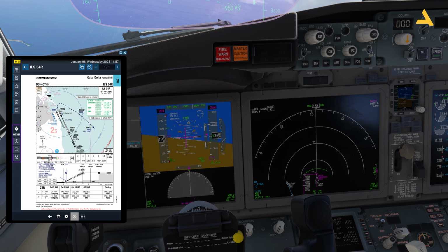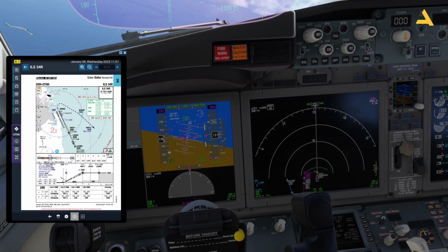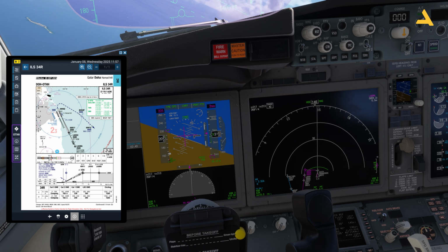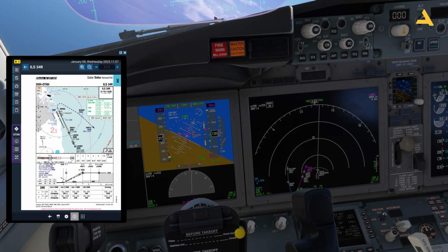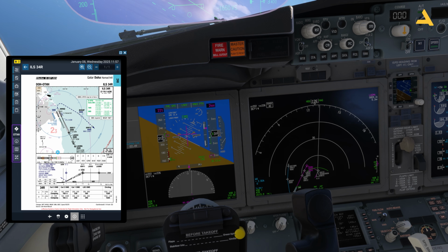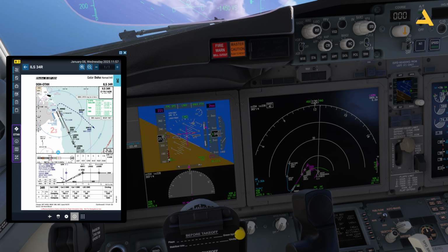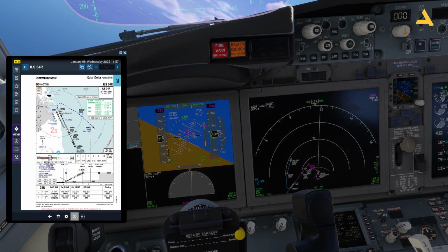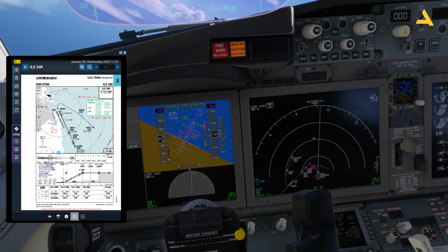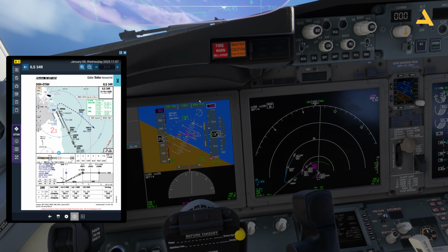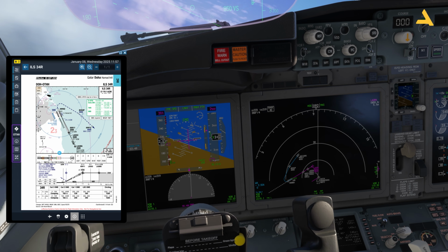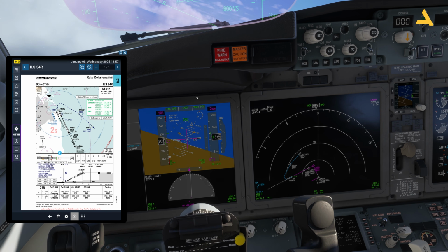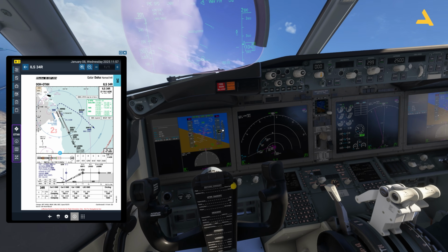And that's it. If I further retract the flaps, it will go up to 220. So that's how you control the speed once the plane is below maybe 5,000 feet. Now you can hear this stall warning. So that's why you should get the flaps. So this was just for the purpose of demonstration.